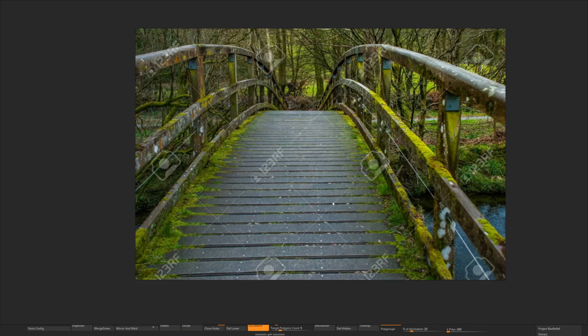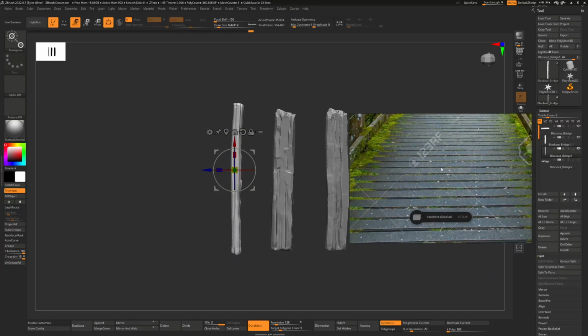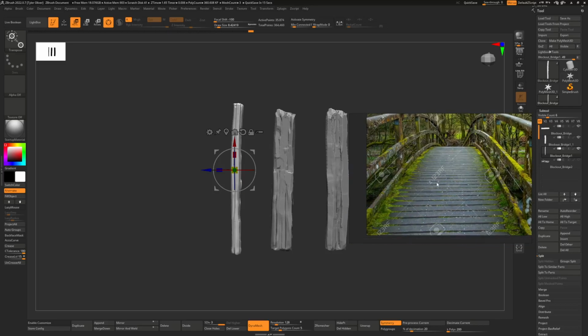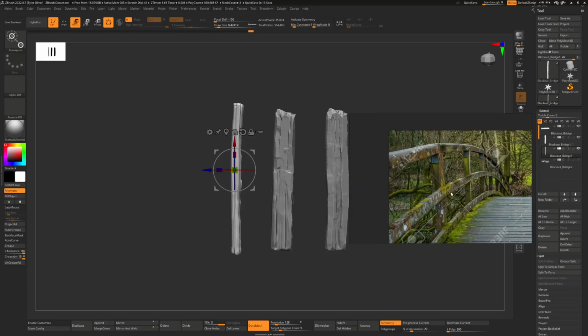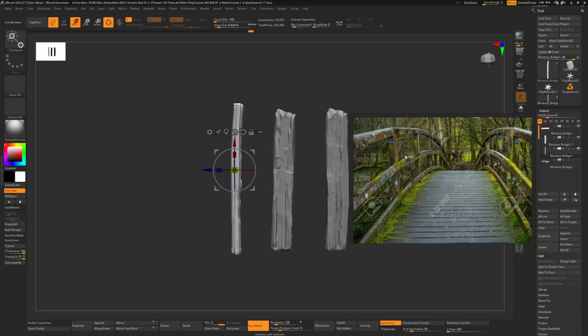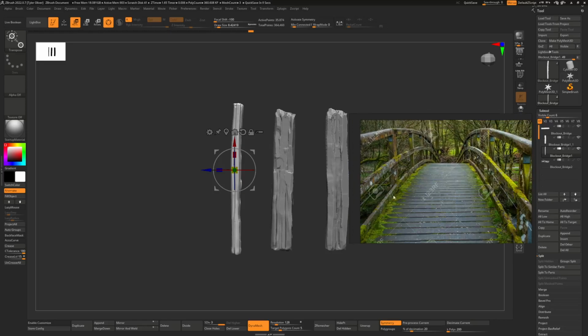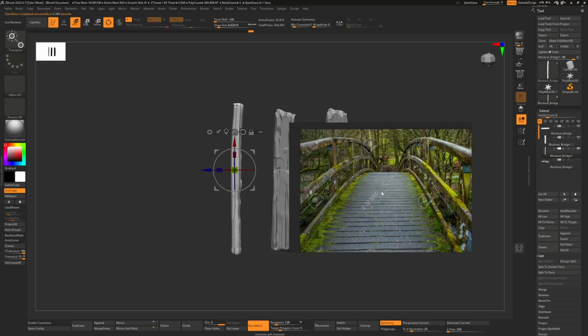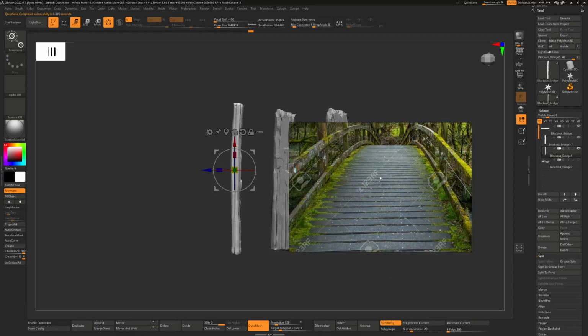So that each plank of wood could have this green moss on each side of the texture, but then you couldn't really use this plank in a different situation. Say you want to use this plank on this side bit as well, where it's completely different, doesn't have the moss directly on the top and bottom. You can't do that if it's directly in the texture. So that's where the mask is going to come in.